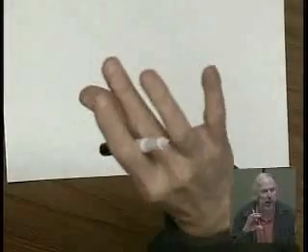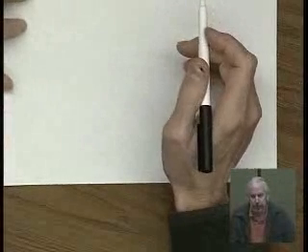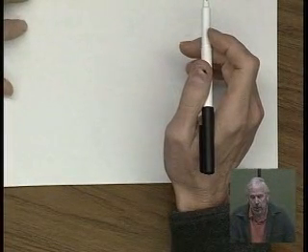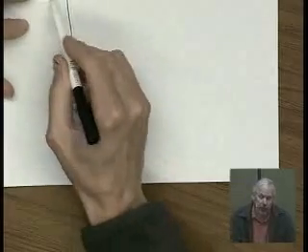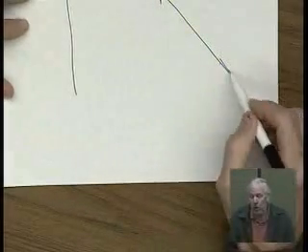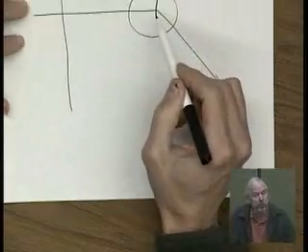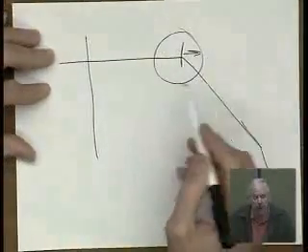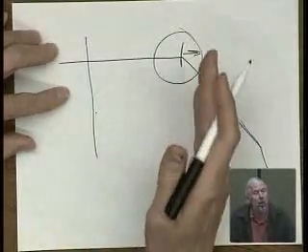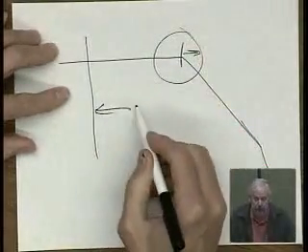All right. Any questions about the project? So let me just say some words about the specs. What I would say, you should basically start with the circuit you had before, because we didn't change any of the output swing specs. All that stuff has stayed the same. We did that for a reason, to make it easier for you this time. What we're asking you to do is the low frequency pole. You'll have a whole bunch of other poles, but we're worried about the lowest frequency pole, and you want to get that as high a frequency as possible. That's the bandwidth of the circuit. The bandwidth of the circuit is set by the lowest frequency pole. That's what we mean by bandwidth, okay?